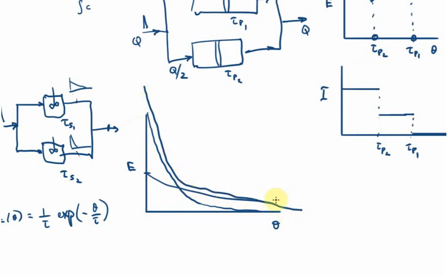And so it depends how sharp this is, how different these space-times are. If the space-times are closer together, then when you do this experimentally, you might not be able to discern this kind of difference in gradient, because it's a continuous curve, and it's the sum of two exponentials. An exponential function can fit this fairly well, but anyway, it actually is the sum of two exponential functions, and so it's not a pure exponential anymore. So that's what we get in the case of CSTRs in parallel.